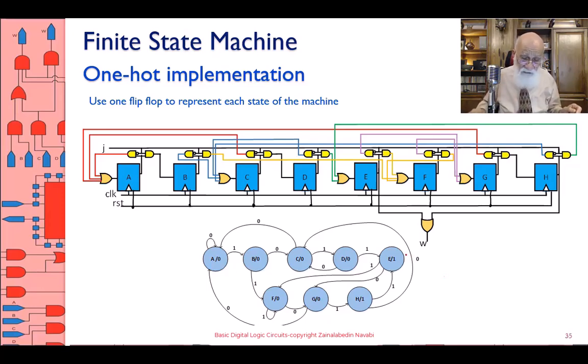And notice that I have two states where my output is 1, E and H. Therefore, what's the output? If I'm in the state H, or if I'm in the state E, the output is 1. So what do? OR them together. Put an OR and take the one input from state H, one input from state E, and you're all done.